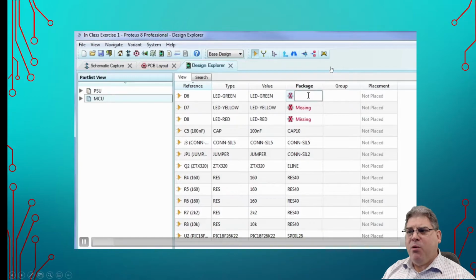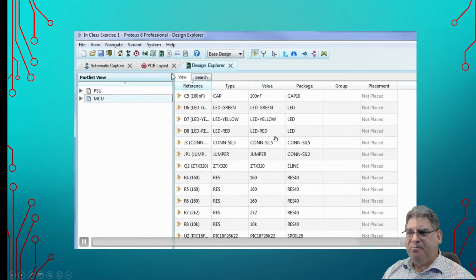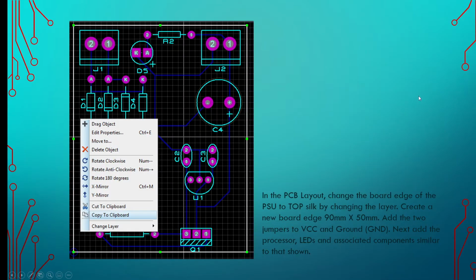But then it's very important once you've moved this footprint that you apply the changes. Okay. And so if you do make a mistake, if I go down here by accident and I make all of these LED, you can discard the changes. Okay. So super powerful tool. All right. Once you have your two LEDs put into position, we can move on to the next slide here,